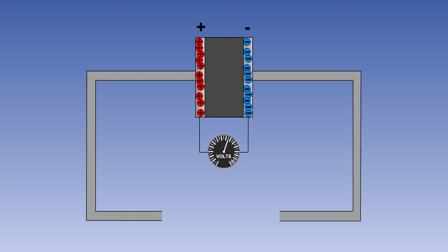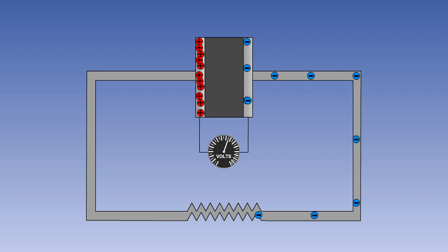If the capacitor is now removed from the supply, it will retain this charge until it is connected to an external circuit, when the surplus electrons on one plate will flow through to replace the shortfall on the other. Notice that the capacitor has discharged in the opposite direction to which it was charged. Remember that electrons do not pass between the plates through the dielectric.